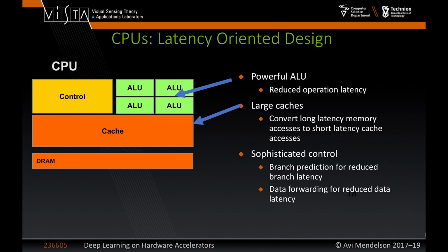And if we look at the way that CPUs are built, you try to optimize the latency. Because we said that even if you have a small amount, a low probability of miss ratio, but you have a long latency, you suffer a major reduction in performance. This is true only if you are looking at the performance of a single thread. But Nvidia said, okay, we have so many threads that we don't care about the single thread, we care about the system. And we have a lot of threads.